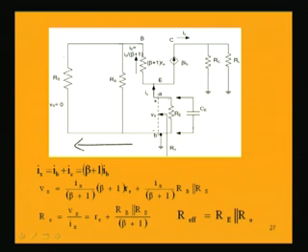When you have to find out the effective resistance across these 2 terminals, you make the circuit inactive, meaning the independent source you make 0, but here actually we will have to apply an external source to know this output resistance looking into the circuit from these terminals A, B, because there is a dependent current source, beta times of IB, which will be having one part of the current which is due to this external source.